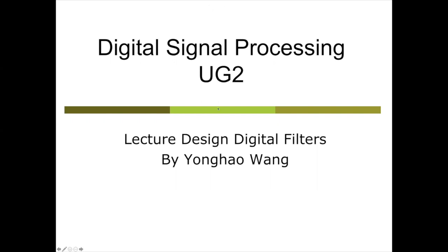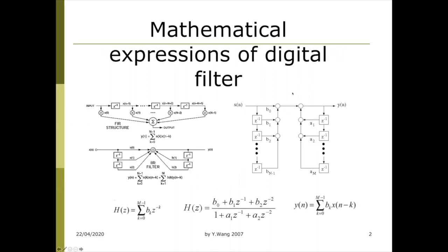So I think before Easter break, I did talk about digital filters in terms of their structure. A digital filter can be represented in various different structures, such as a flow diagram, because literally what a digital filter does is take an input signal, apply various delay lines, multiply by different coefficients, and then mix with different delayed channels, multiply by different amplification or attenuation factors, and synthesize the final signal. Then that's basically a digital filter.